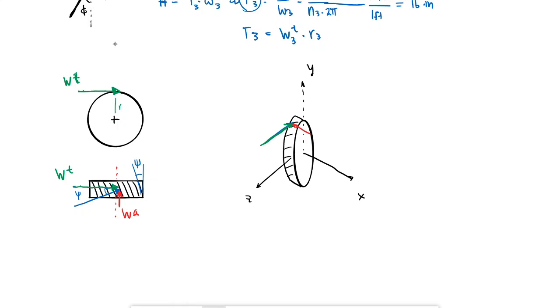So what I would actually have is something that is perpendicular to the tooth. Okay, so if this is the tooth at an angle, I would have this vector that I can get the components of for Z and for X. Okay, same ones, WT and WA. Okay, but it's a distributed load, is what I'm trying to say here.